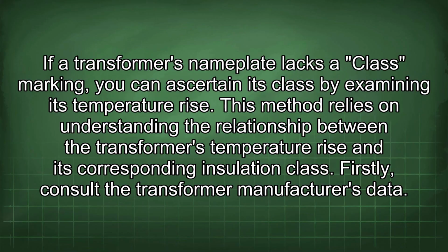If a transformer's nameplate lacks a class marking, you can ascertain its class by examining its temperature rise. This method relies on understanding the relationship between the transformer's temperature rise and its corresponding insulation class.